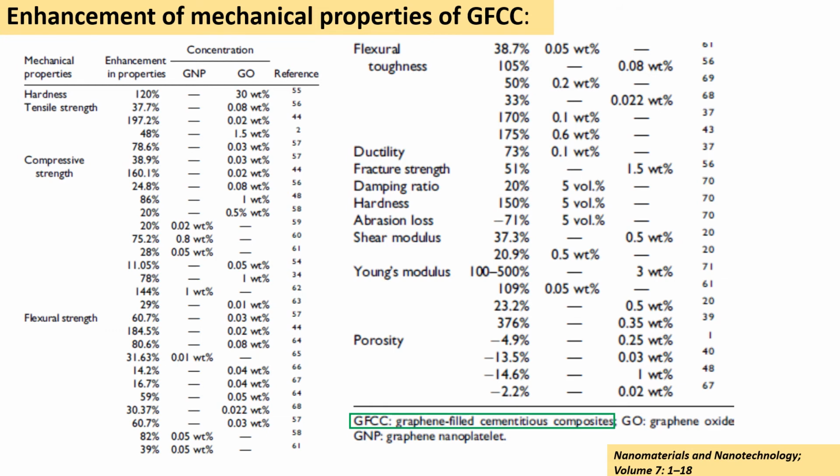So in a matrix, maybe a polymer matrix or organic matrix, or in a cementitious or concrete matrix, by virtue of this high surface area and unique functionalizations, it is able to interact very effectively with the surface of the matrix. This eventually leads to very good bonding or connection by virtue of covalent and non-covalent interactions, and the high surface area can also serve as a potential point of nucleation and growth of the crystals. And definitely there's also densification.